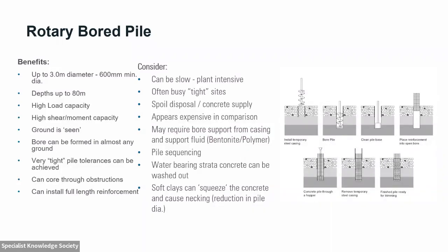There's no real limitation on the depth. We've got 80 metres there, we've noted, but it could be longer than that. It's all relevant to the Kelly bar that you've got on your rig, and the Kelly bars extend. So you can dig much deeper. If you're in ground that supports itself, you can also see down the pile. So you can dig a hole, you've got an open bore, you can actually visually see down the pile.